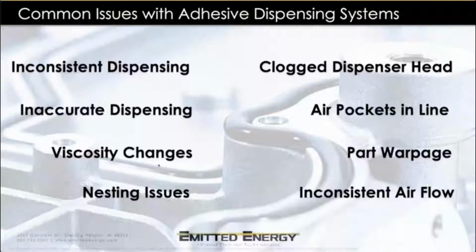Viscosity, we want to heat this material up to a certain temperature, and depending on your material, you have different parameters, of course, of what temperature that adhesive needs to be to properly be dispensed. And when there's variation in the line, now you could have plant variation, you could have ambient temperature variation. There's a lot of things that could change that can make that change over time. You could have actually a problem in the heater system that you wouldn't know about until you do the leak testing, and you have to throw out those parts. So there's a lot of issues with viscosity.